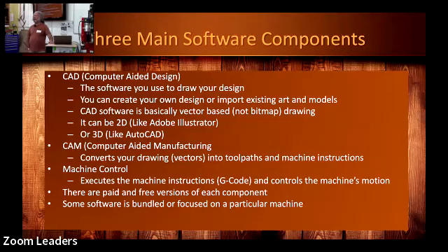Yep. So Craig highlights the fact that if you're going to go buy a machine, make sure you understand what it is that you're going to do with it, and make sure that the capabilities of the machine match your needs. The issue that Craig ran into was limited Z-axis height. They'll spec what the height is. They might say 8 inches, but that doesn't include the bit, might not include the collet, might not include some other things. So you've got to make sure that you really understand what kind of clearance you're going to get. As an example, what is that bed size? Is the bed size the nominal area? Can the gantry actually reach it? Can I have material there? If you're going to get out towards the edges of the capabilities of the machine, in particular, you need to understand that.